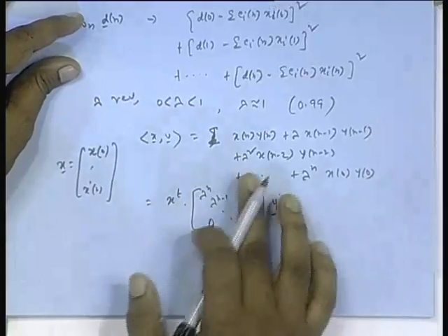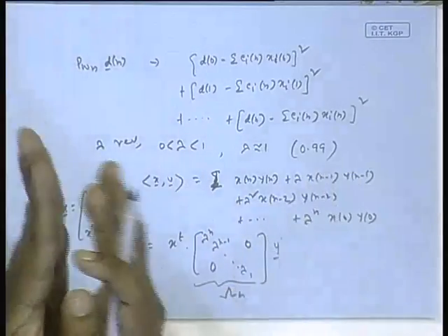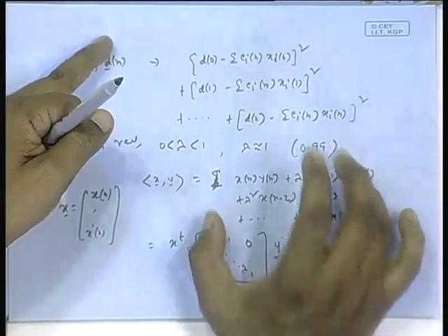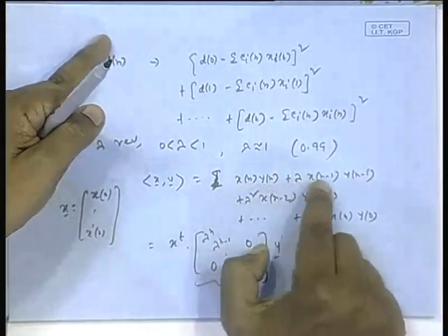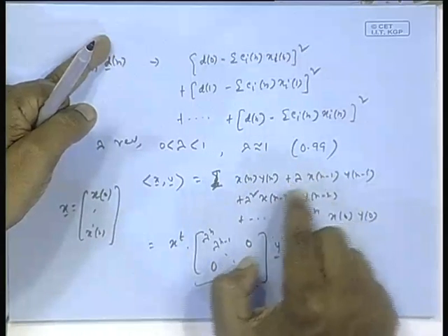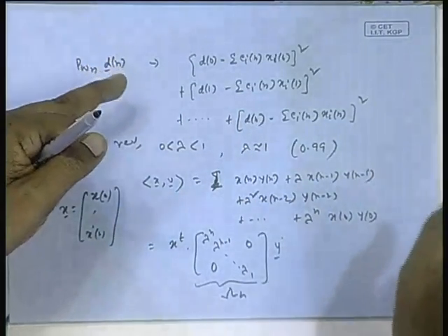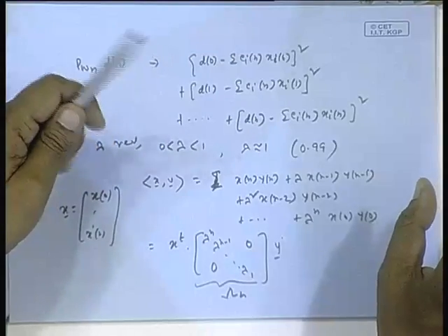If you use this in an inner product and make it a variance, and that too the variance of the error, because after all, while computing the projection, you will be finding the error vector and minimizing the variance. In that variance, if you want to forget the contribution from the remote past, n equal to 0, n equal to 1, and concentrate mostly on the current ones, then these weighting terms will take care of that. In the sum of square, the dominating part will come more from current ones, x n y n, or maybe lambda times x n minus 1 y n minus 1. If it is variance, x n square, then lambda times x n minus 1 square, lambda square times x n minus 2 square, maybe a few more terms; other terms will be sufficiently suppressed. So lambda will be part of the algorithm.